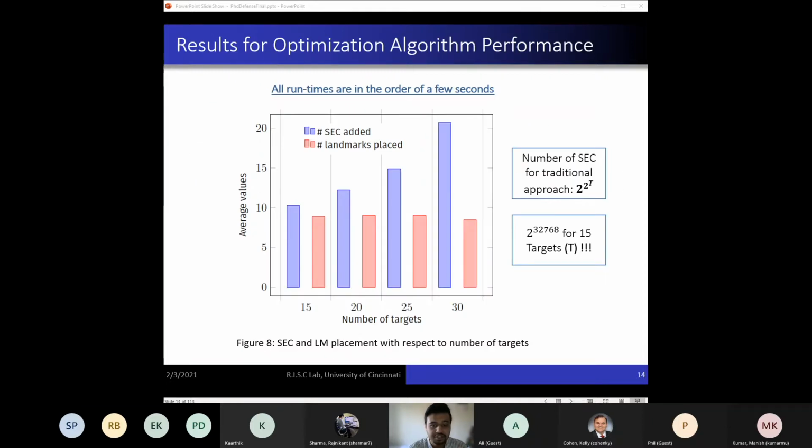Now, figure 8 shows a very interesting result for the subtour elimination constraint. For subtour elimination, we use a robust dynamic cut generation technique. That is, the SEC or subtour elimination constraint is initially relaxed. We find a feasible solution to the relaxed problem. If a feasible solution is found, then we check whether that feasible solution is also a valid solution for the actual problem. If it is not, then we introspect the subset of waypoints, the waypoint sequencing, that violates the SEC.